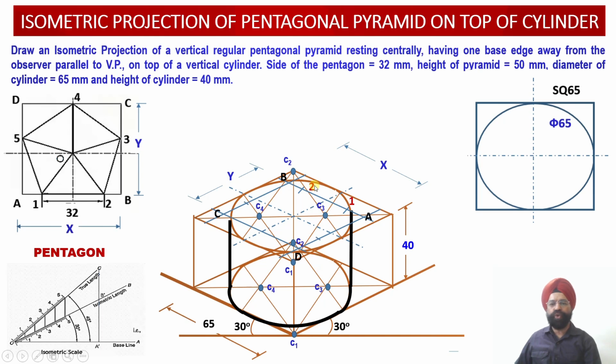So let me mark the next 2 points, which are equal to, please check, B3 and A5. Similar to A1 being equal to 2B, here we have B3 equal to A5. So that is why we have marked both of these points simultaneously, this point and this point. Let me mark the points. The distance of B to 3 and A to 5 will be equal. So this is A to 5 distance, this is B to 3 distance over here. And we can see in the true construction also, B3 distance happens to be equal to A5 distance.